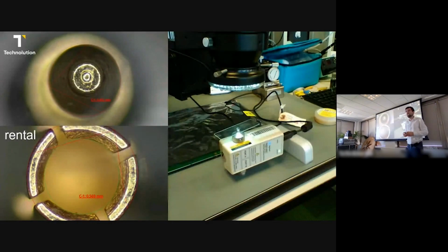Now, did you still worry about this case? I did. I think someone has still connected a normal SMA connector on it. You think someone connected the normal SMA connector to this? Then you really do destroy it. And in which way do you destroy it then? Because the dimension size of the SMA connector pin is not well defined, compared to 2.9 or 2.4. And in what way will you damage the female connector, for example? Yeah, you will bend open the spring pins.